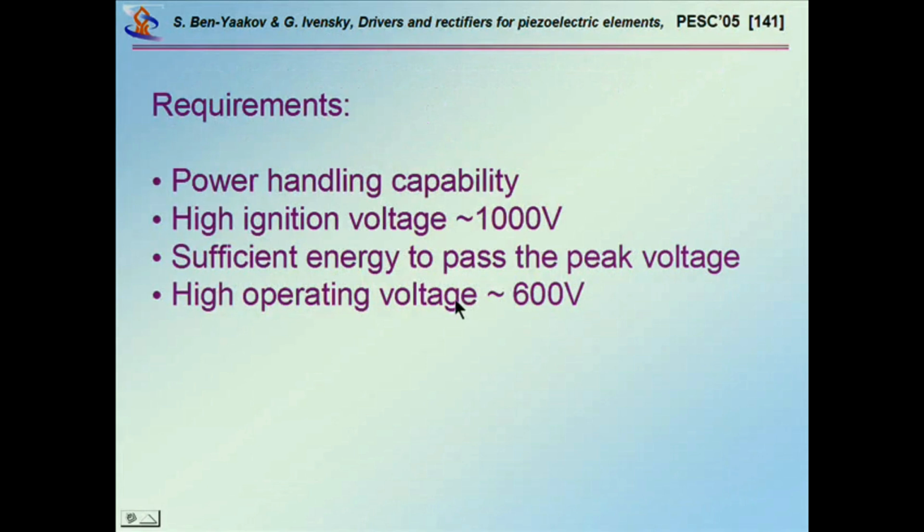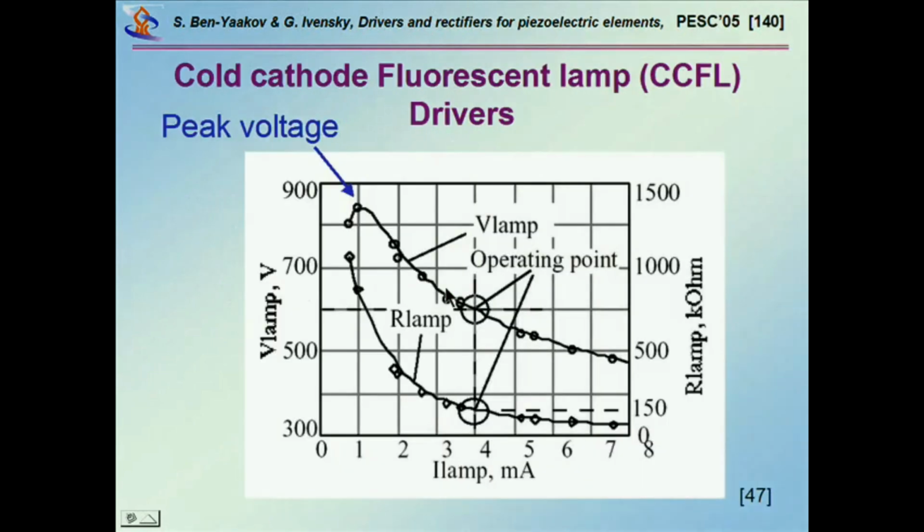Another issue. This is what I've just said, that you need, of course, ignition, and of course, you need the piezo to deliver the right power. In this case, say about 4 milliamps and 600 volts.